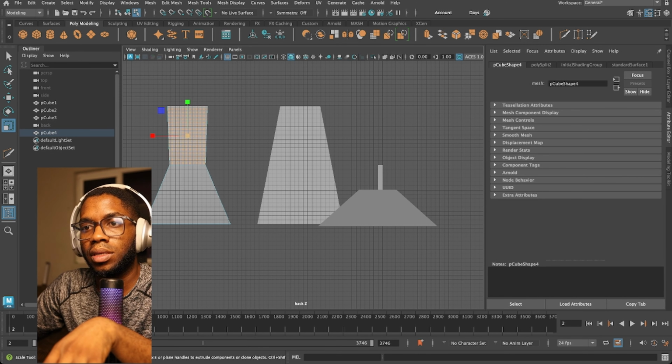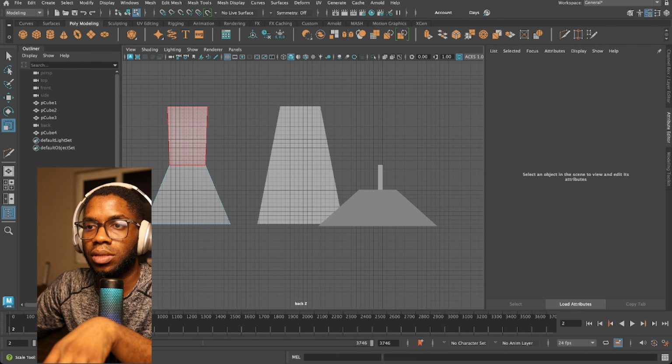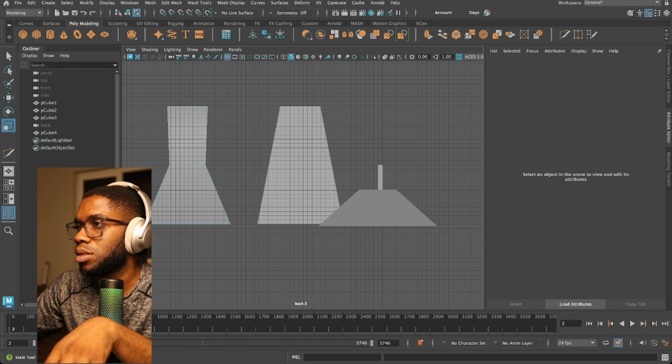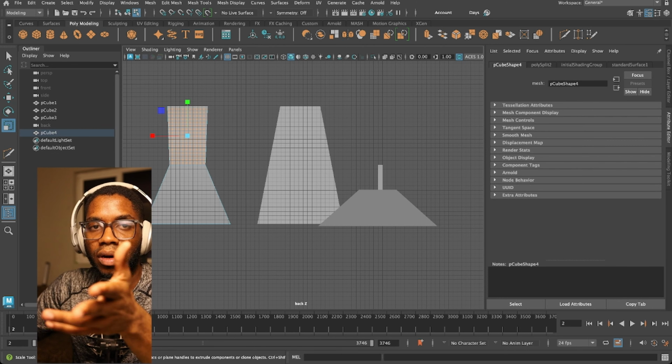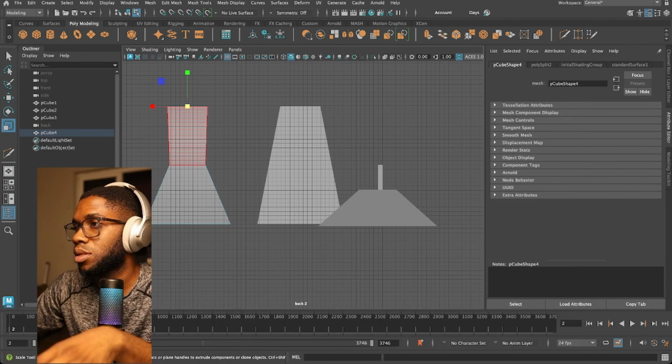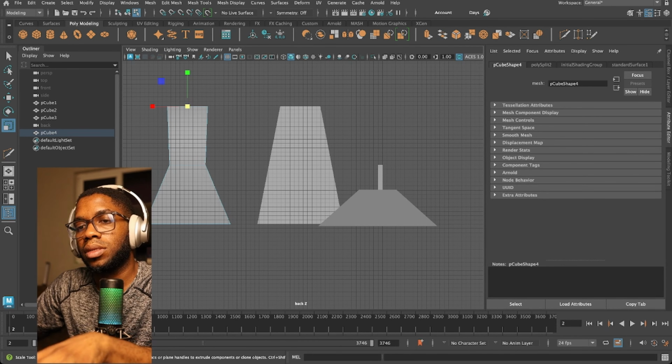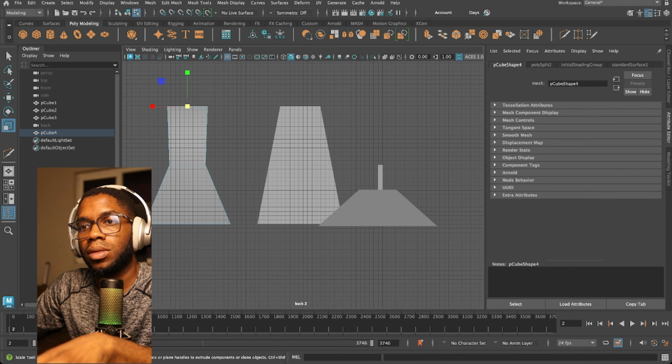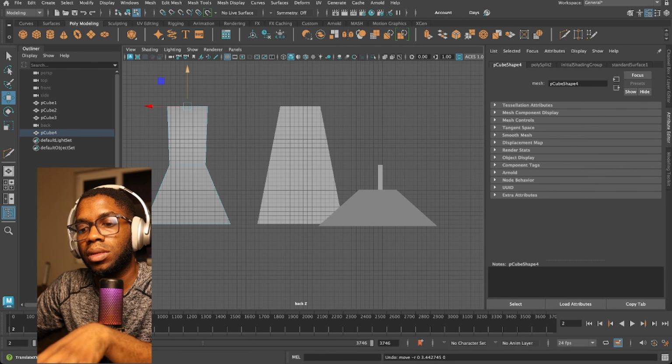If I go like this, let's say I can't touch, I would have to go back into the perspective mode to click this, the top of this face. If I go like bam, I know all the faces are touched. I go control for the negative selection, I know that the top is selected. So now control E to extrude again.